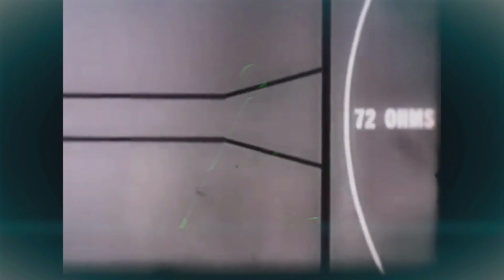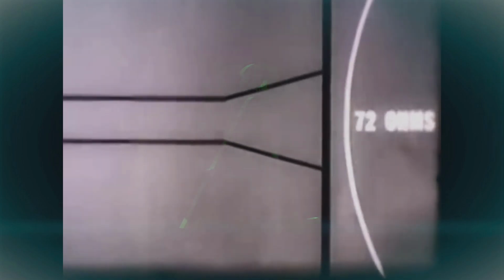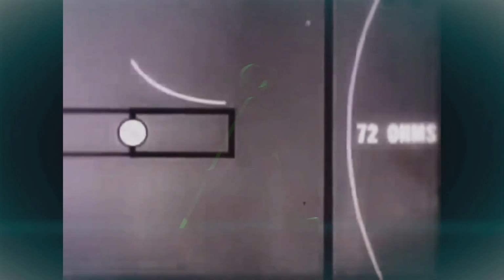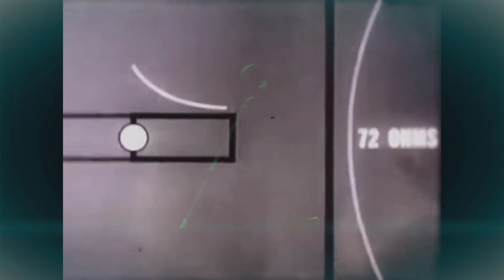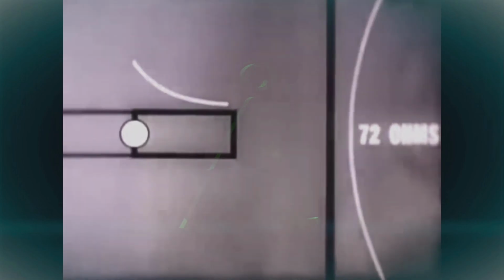Another method of impedance matching employs two lengths of metal tubing called a quarter wave matching transformer, or Q-bars. These tubes are merely the twin wires of our old friend, the quarter wavelength resonant line. In this closed line, the impedance curve is minimum at the closed end and maximum at the other.